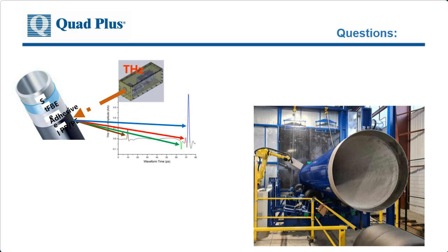Yeah, so typically these will be done offline, and they're destructive testing. So they're in handheld devices. They have to wait till the pipes are fully coated, and they'll be using a handheld device that is only measuring a few spots along the pipe. And that's the major advantage of using this system: you're getting almost 100% full coverage of the pipe, multiple measurements averaged over time, instead of a person using a handheld gauge or destructive testing and just testing a few spots on the pipe itself.